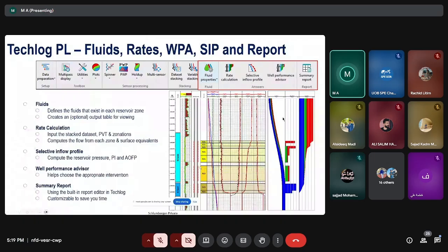While, you see this perforation, it's producing like a mix of oil and there is like some of the gas. And this gas, it might be liberated or it might be even free gas. And so on. So you're going to have a clear idea about every meter of these perforations. What's the type of the fluid and how much fluid is it producing or contributing and what the direction of it. And this is our main objective of having the PLT. So you're going to evaluate the downhole conditions and the production profile of your wells.